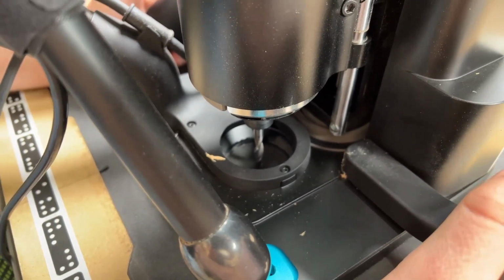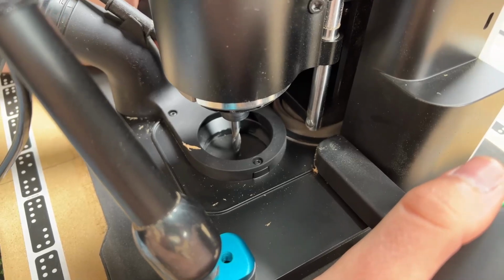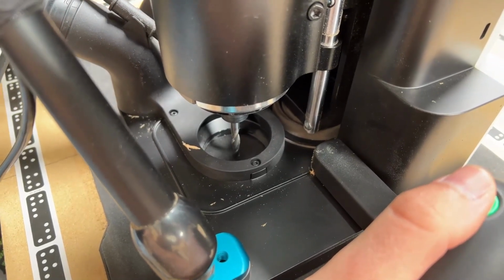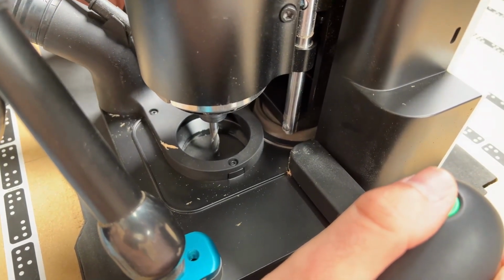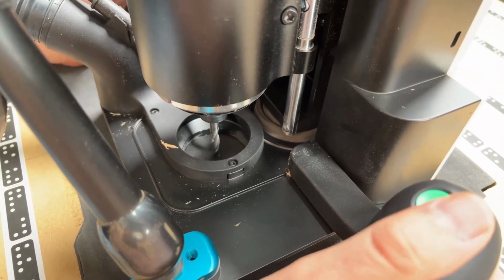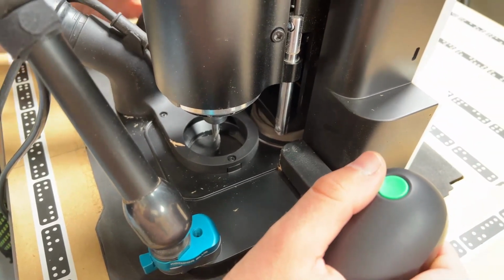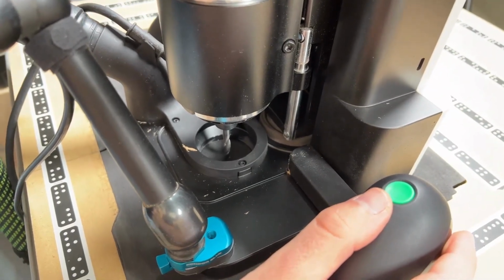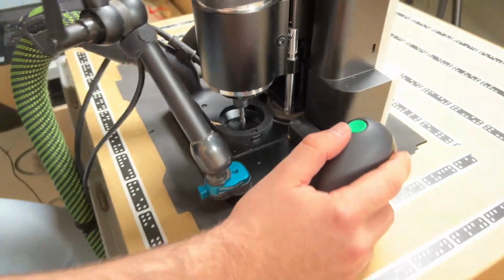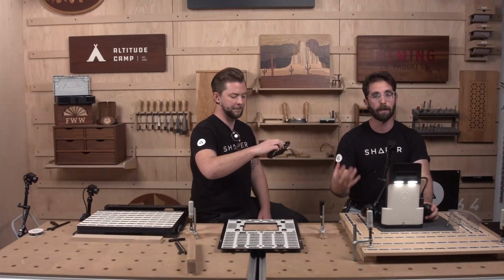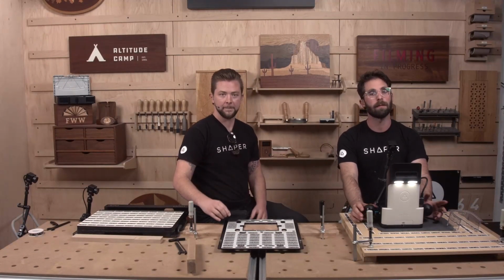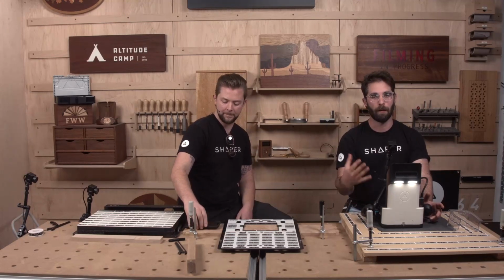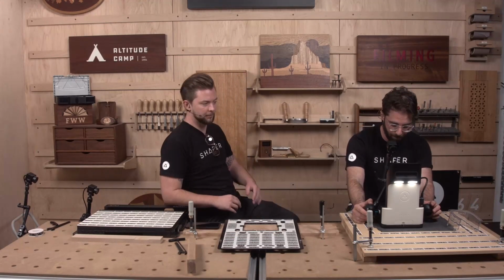And basically the way this works is a short button press will move the spindle a very small amount. Like that's a short button press, very small increments. As I hold that button, it's going to speed up. It's going to move more quickly. So if you have a very deep pocket that you're trying to Z-Touch into, if you hold that button down for longer, the spindle is going to speed up.